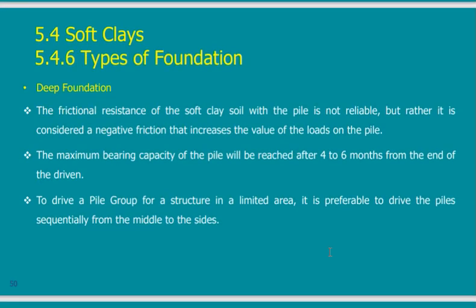Deep foundations is the best type, of course. For deep foundations, we have two types of elements that would help me in carrying the load. What are these? The friction along the pile. If you have a pile in the ground, then this pile is surrounded with soil all around. So this pile will be carried by the soil around it. And at the same time, the end of the pile will rest on the soil. So the end bearing of the pile is another portion of the load that is carried.